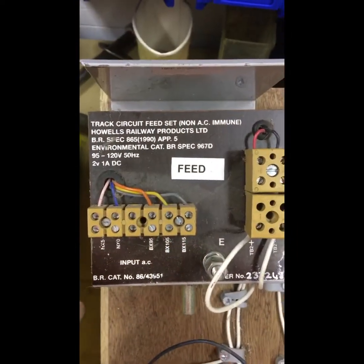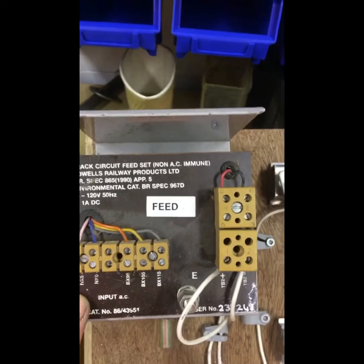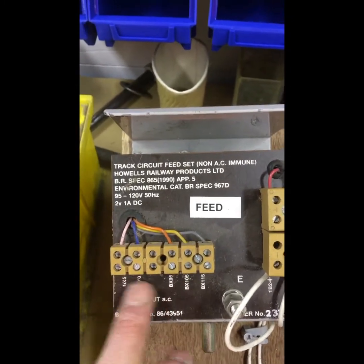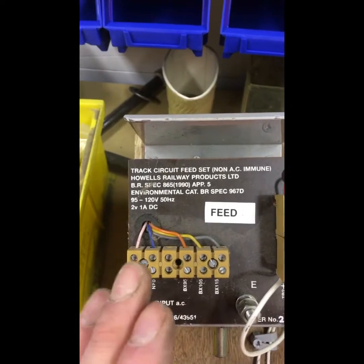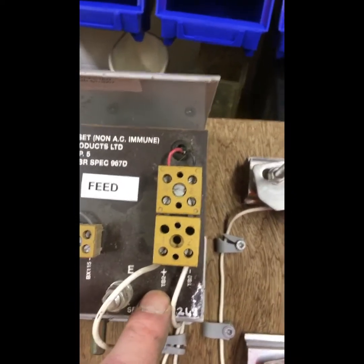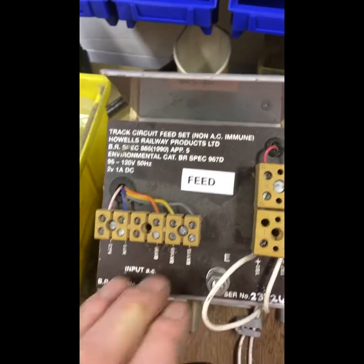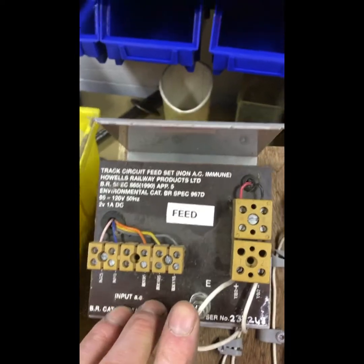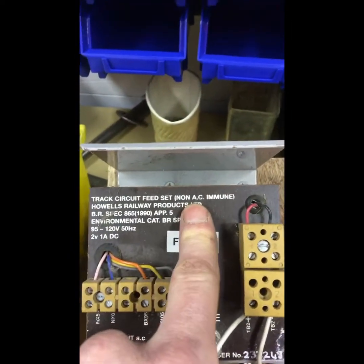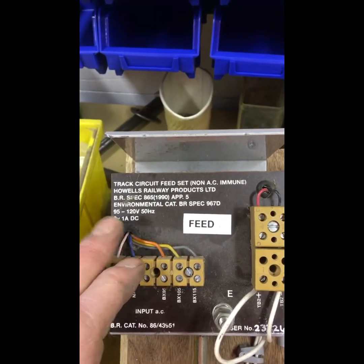This is a slightly older but slightly different track feed set. Here you have your 110 input again, with your balancing settings on your primary side, so you can raise or lower the voltage to match. And on your output side again, your track positive and track negative outputs. Just a smaller unit. This one doesn't have a long or short setting. It's not AC immune, as you can see from the label here, and kicks out about 2 volts, 1 amp.